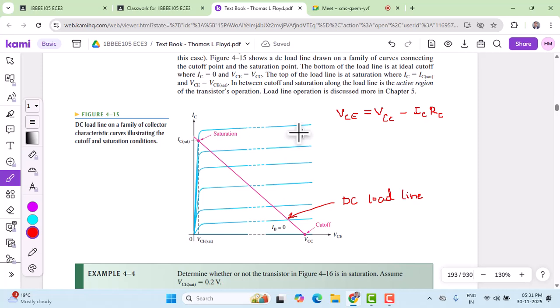Okay. And here we have both variables, PD max. PD max follows this bent, arc-type region, and any current and voltage that falls above this arc is unsafe. In that way, this graph helps us think about the BJT operation, the safe and unsafe regions. So the gray color is the unsafe portion, and the white color is the safe portion for the BJT to operate.